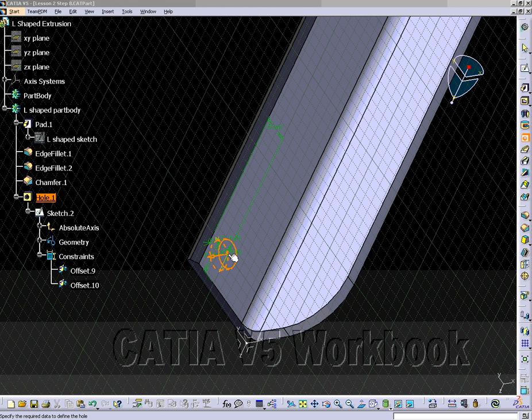You now need to accurately position the hole in the correct location. To do this, you will use the constraints created previously. The constraints you have created will most likely be crowded together. In fact, you may not even be able to read the constraint values. This can be fixed by zooming up on the constraints, selecting one of the constraints, and dragging it away from the collection of constraints. Then select another constraint, once again dragging and dropping it far away from the other constraints so that it can be read and selected.